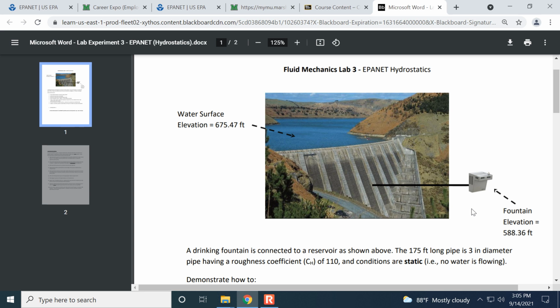So if there's 5436 pounds of force in a square foot, how do we determine the number of pounds of force in a square inch? What's the conversion factor to get PSI from this? What is it? Multiply by 144.